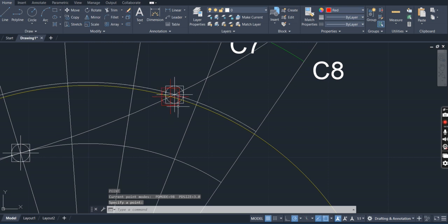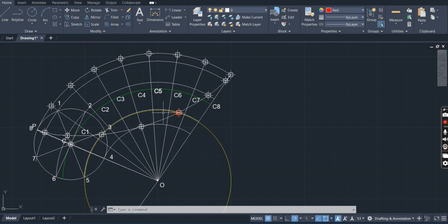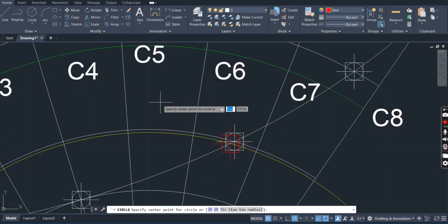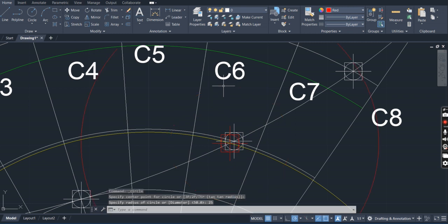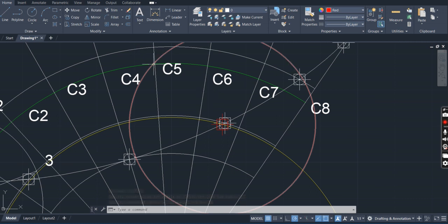So where we need to draw normal and tangent, here you can give that as P1, like we have already given P1, P2, and give here some X. So X, go to text. Afterwards, go to circle again. Use this point as the center point, 25 mm as radius. Construct one circle. So that circle will cut the center line at one point. This is the point. I'm using PO, enter. So this is the point.